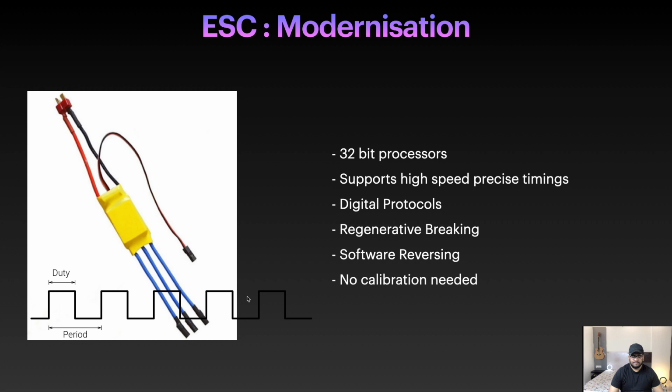Doing the calculation, and you are flying a drone at 100 miles per hour, you need very fast processing time. So this is not the way to go. The way to go is digital. You just tell your ESC, I want my motor to be at 33% RPM, and it understands quickly and it does. That is only possible if you are communicating over digital. So both systems are digital. The flight controller is digital, the ESC is digital, so why should they speak analog? So yes, digital protocols are the way to go.